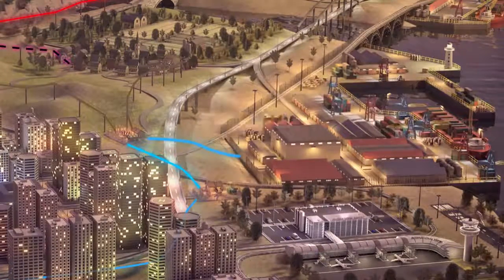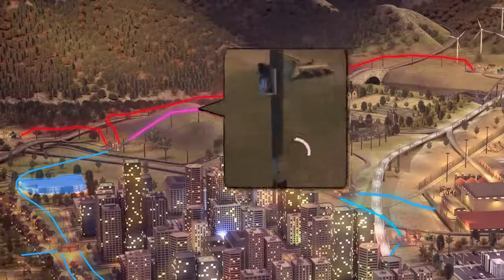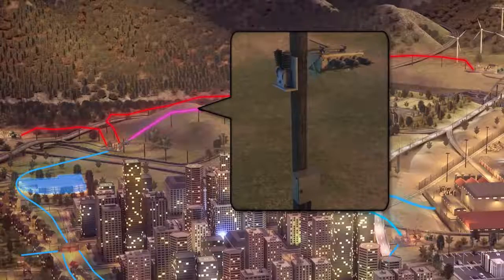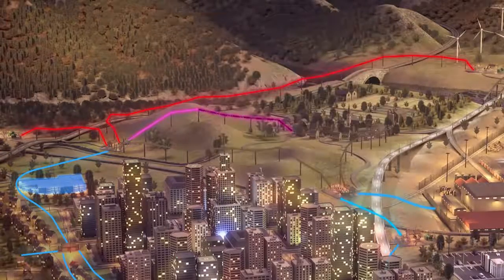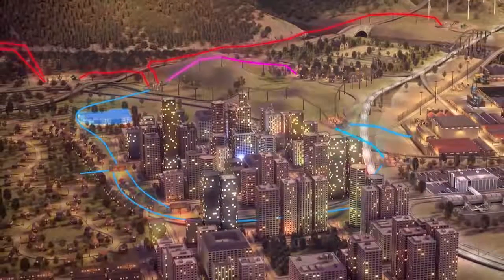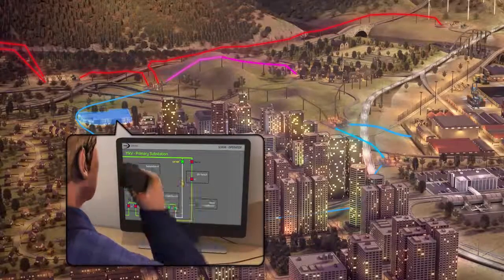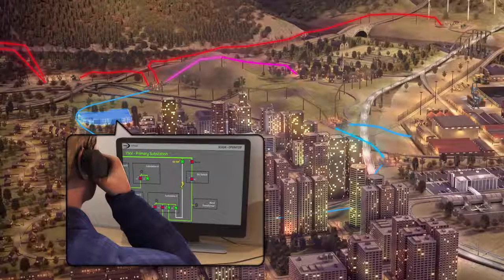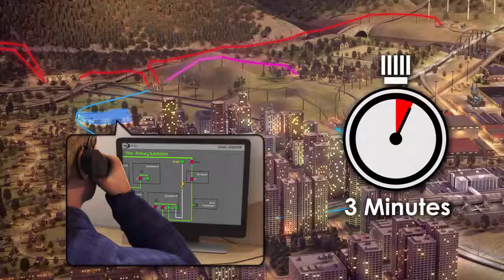In order to avoid overloading one side of the network, the operator chooses instead to close the GX switch on the backfeed to the rural community to reinstate their supply. Supplies to all affected areas are now complete and the faulty line is safely isolated from the network, allowing the operator to arrange for a repair. Typically, the network will be sectionalized and power rerouted within 3 minutes of the original fault.